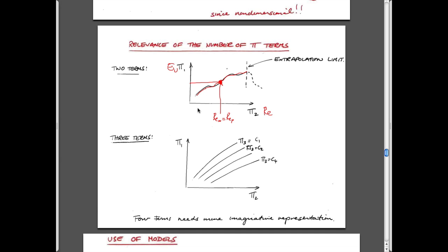If for a model you do a whole bunch of different experiments, then you can build a curve that looks like this, which is true for that particular, say, geometry of the model. And so it doesn't matter what Reynolds number your prototype is going to work at, because you always have the result for a whole span of Reynolds numbers.